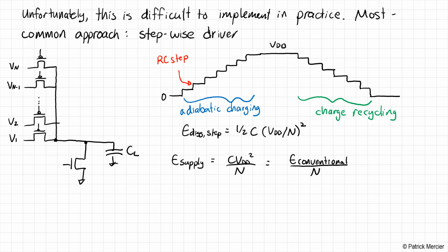So again, this is a very, very cool, exciting way to really save energy. Now, as I mentioned, how do you generate all of these different supply voltages? Do you need N DC-DC converters? Well, probably, actually, in the basic cases, yes, you do need N DC-DC converters, which adds significant overhead to your circuit. How do you route N different power supplies to all of your circuits and so on? This is actually rather complicated. We published a paper a few years ago at the International Solid State Circuits Conference in which we developed a staircase circuit that used an internal switched-capacitor network to automatically generate these supply rails in an efficient and very effective and low area way. We were able to demonstrate in microprocessor kind of loads that we could reduce clock power by around 50% or so. And this was with a small handful of steps.